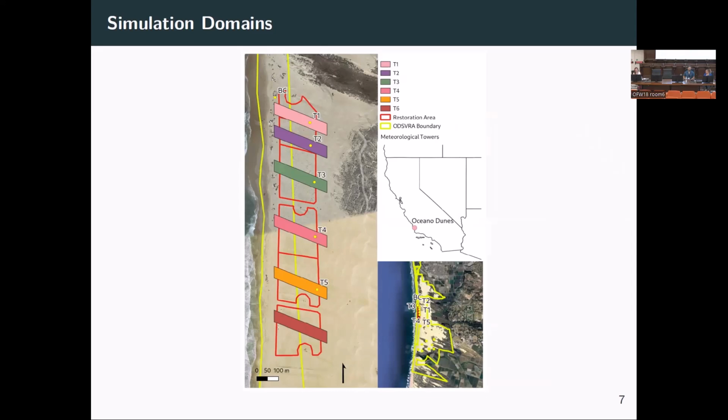Yeah, so that was actually really difficult. The Y plus is around 90. We did use wall functions, and on average, computed with OpenFOAM's function object, and I ended up using cfMesh just because I was willing to sacrifice. I was having a lot of boundary layer collapse with Snappy, and I was worried about the shear stress. So we sacrificed matching the surface exactly a little bit to get better shear values.